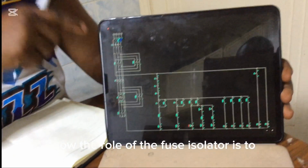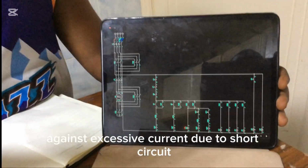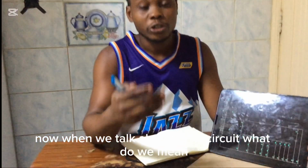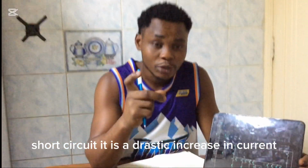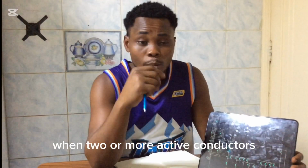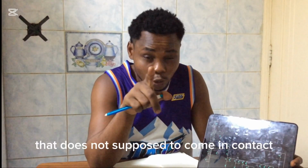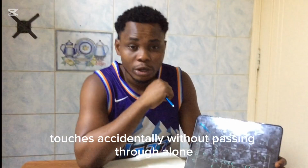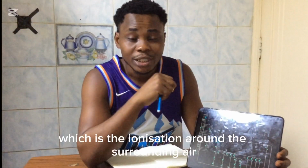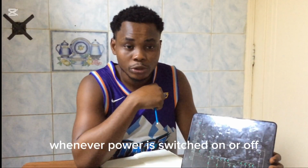Now the role of the fuse isolator is to protect the entire circuit against excessive current due to short circuit. When we talk about short circuit, what do we mean? Short circuit is a drastic increase in current, from 10 to 100 times its nominal value, when two or more active conductors of different polarity or different potential that are not supposed to come in contact touch accidentally without passing through a load. Some sparks, those sparks are called electric arc, which is the ionization of the surrounding air, made live whenever a coil is being switched on or off.